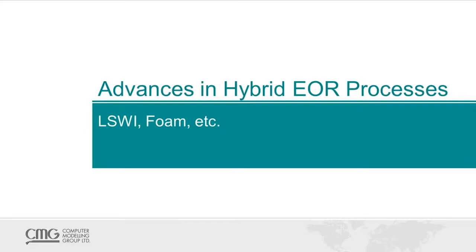In recent years, next generation carbon dioxide EOR technology and advances in hybrid EOR processes could potentially increase the oil recovery from the reservoir compared to conventional methods. The combination of carbon dioxide and low salinity water injection, or foam-assisted carbon dioxide WAG processes, are a few examples of these advancements.